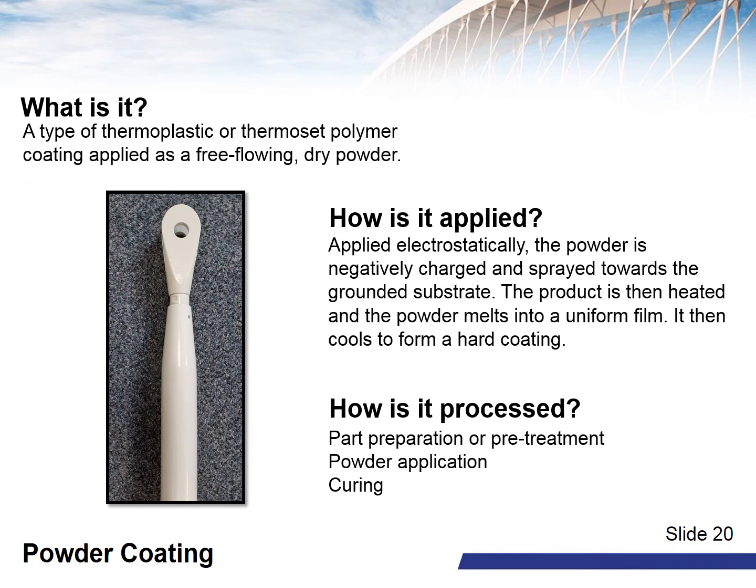Prior to coating, the steel will require the removal of dirt, oxides or welding scale. This is achieved by degreasing, etching and rinsing. However, extra bonding can be achieved by pre-treating with phosphate or chromate. Blast cleaning is also a common surface preparation for this type of coating.